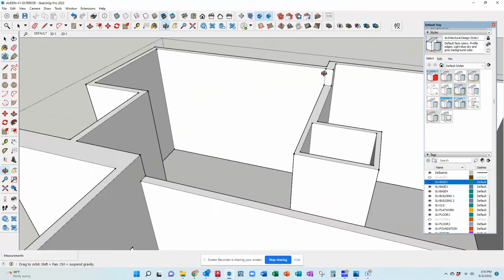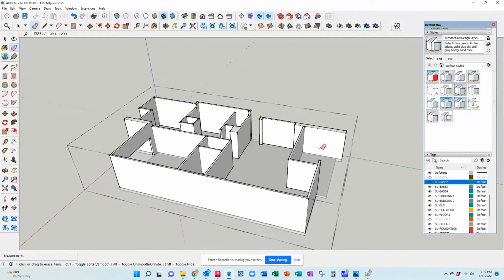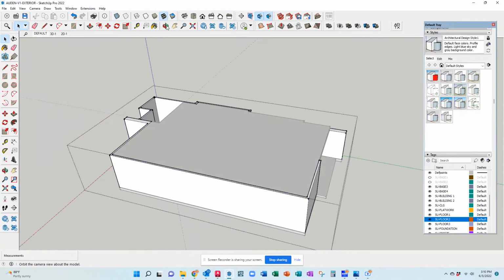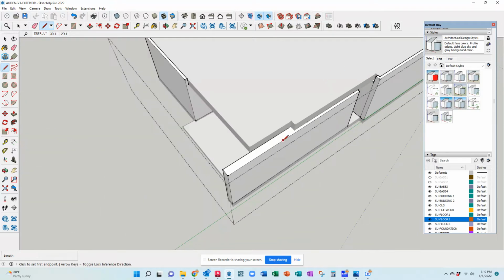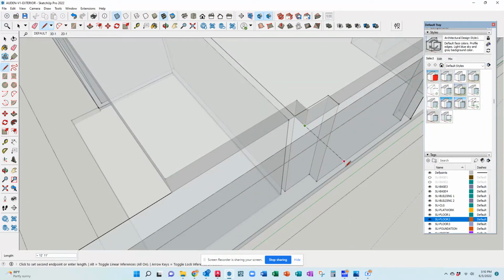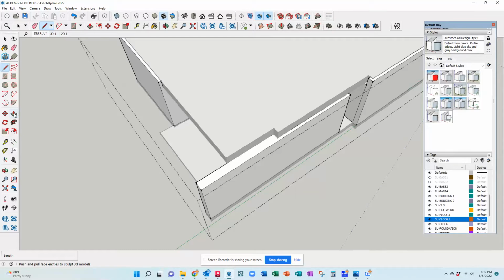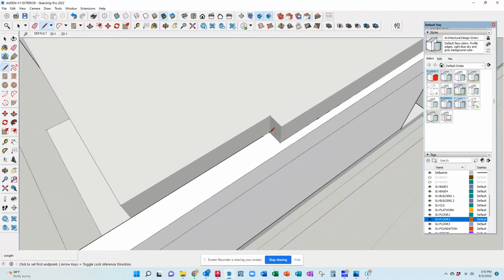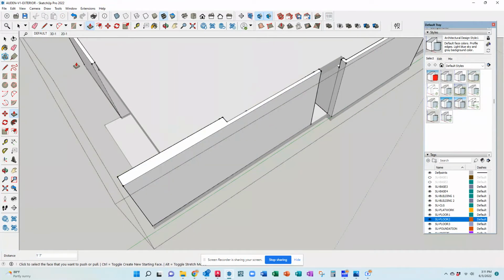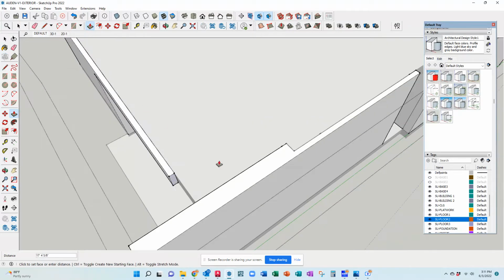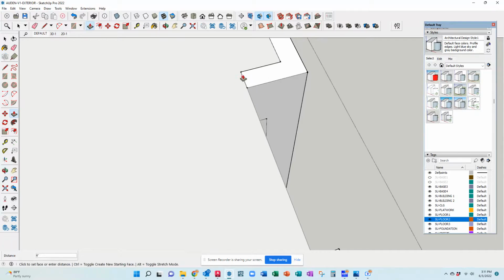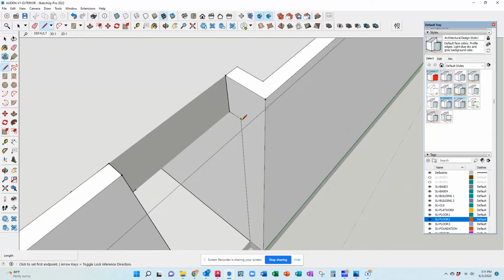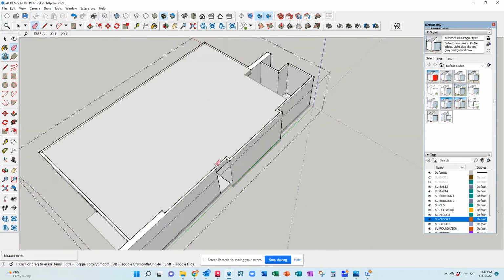If you're familiar with SketchUp, you'll know that groups and components and proper tagging of layers is key to success, to be able to turn things on and off and see various views and work through the model without elements in your way, so to speak. It's hard to work on interior walls if you can't turn the roof off, so the roof has to be on its own group and tag so you can turn it on and off. And it just helps with modifications later too, because there most certainly will be as we work with the client and find out their likes and dislikes.